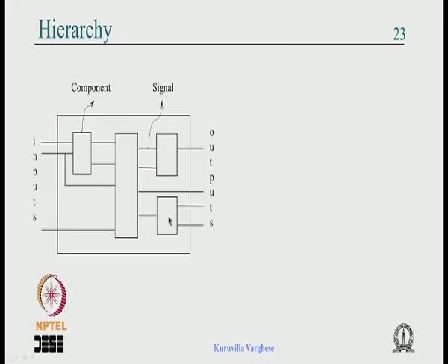So this is what we have looked at when you have structural coding, which is used for top down design. You have a top level entity with names and the ports. This is composed of some interconnection of components. So you need to declare in the architecture declaration region the various components used, that is basically a name, again the input output ports, and various internal signals. And in the statement region we instantiate distinct components as required and interconnect them. So we somehow show a netlist. That is what we have seen.